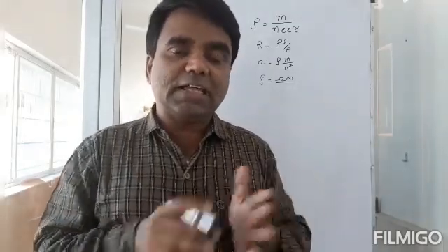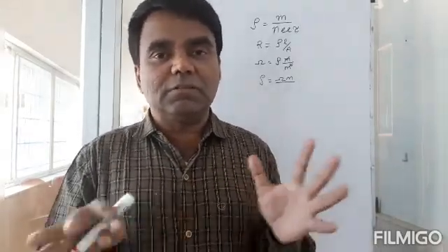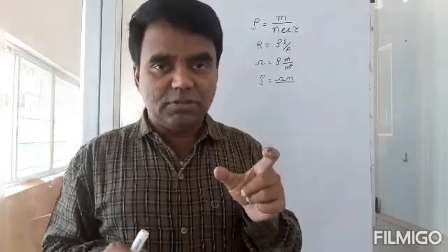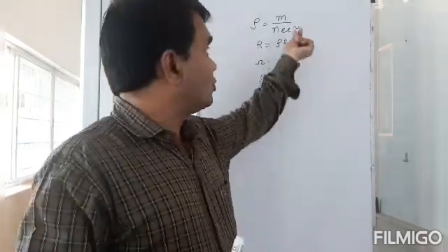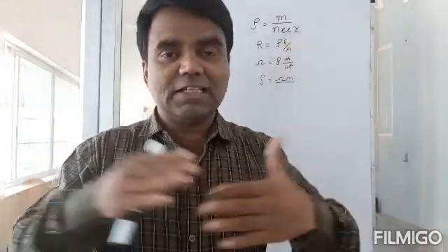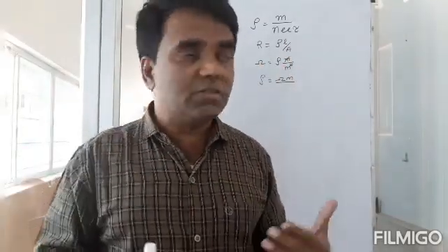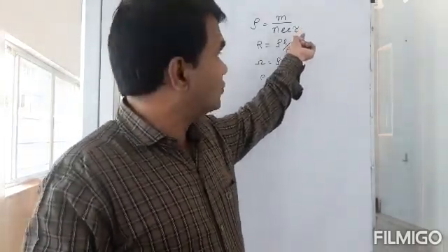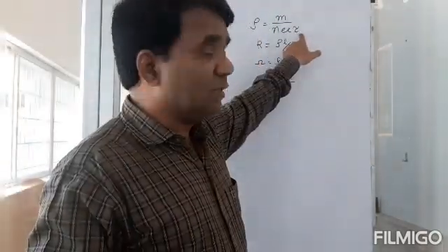If the electrons move fast inside the conductor, then it can increase the number of collisions per time, meaning that the time per collision reduces. So if tau reduces, that means that electrons are moving very fast, which will be the case when the temperature of the material increases, and because tau decreases, then rho will increase. So as the temperature increases, tau will decrease, and rho will increase for the same material.